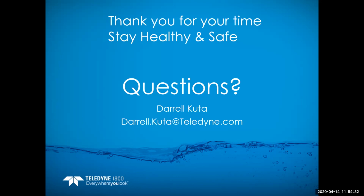Next question: in an effluent flow meter application in a round pipe, the water is apparently so free of debris that a 350 Doppler velocity sensor can't get accurate results. Would the 360 laser flow sensor be subject to the same problem? What I've found is that the laser flow sensor is able to read in applications that the continuous wave Doppler sensors have not been able to read.